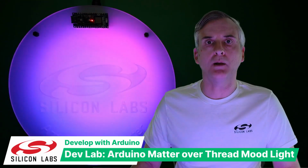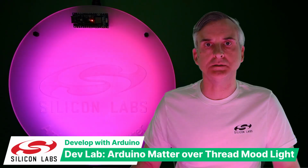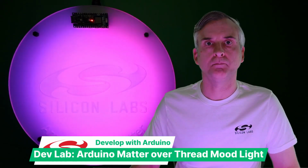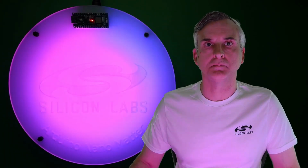In this video, I'll walk you through the creation of a Matter over Thread device using Arduino's Nano Matter board that features Silicon Labs EFR32 MG24 multi-protocol microcontroller. The Silicon Labs core for Arduino already includes many different device types, and those that are not included, we're working to add. So for this video, I'm going to create a single physical device with two logical colour bulb endpoints.